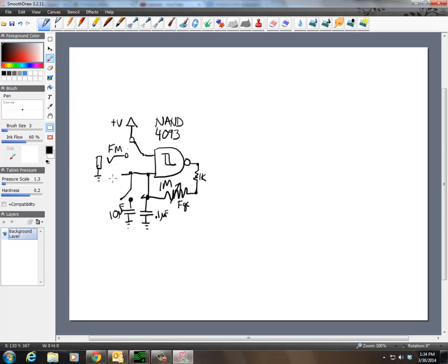And then a third thing we can do is have a diode coming as an input from another oscillator, and that would make an oscillator sync, because then these capacitors would be able to discharge through this diode when it was in the correct state.